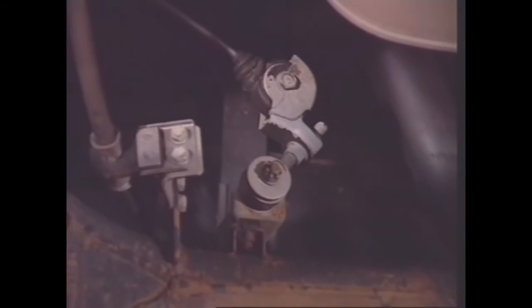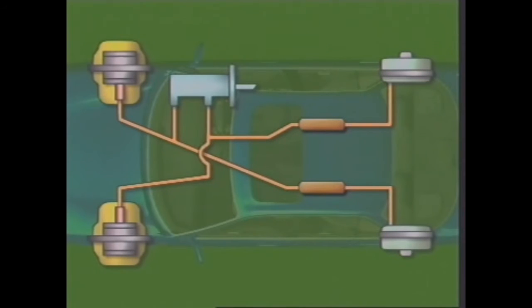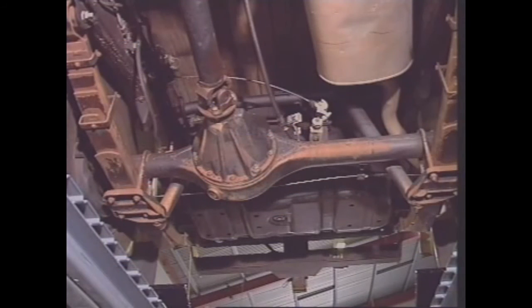The load-sensing proportioning valve is usually located in the rear brake circuit on the chassis. A diagonally split system may have two load-sensing proportioning valves, one for each brake. The unit is mounted on the chassis around the rear suspension.